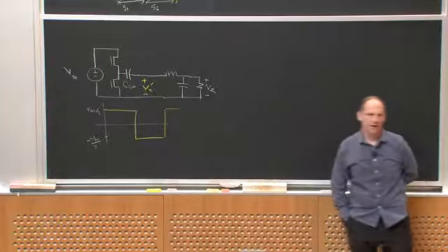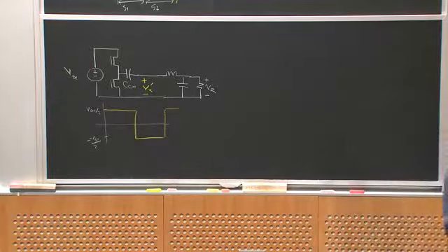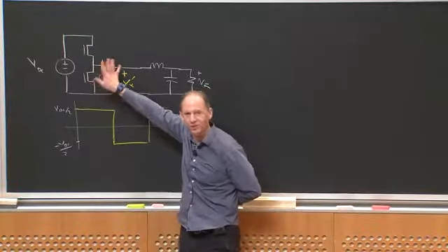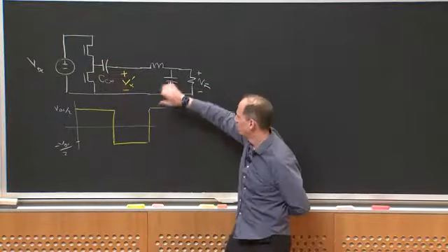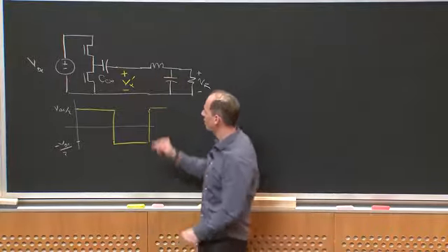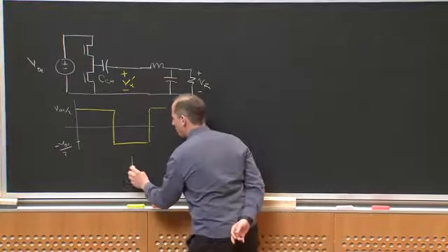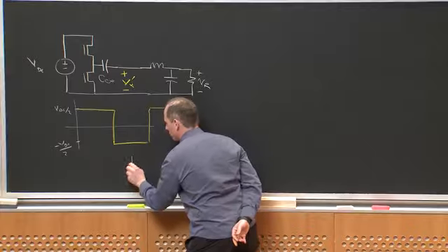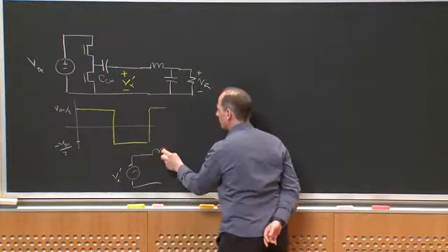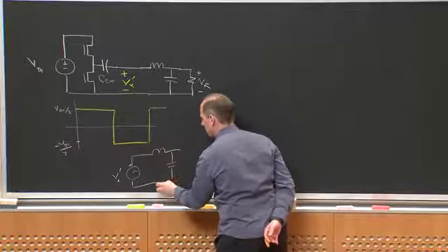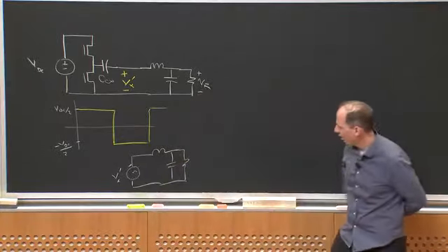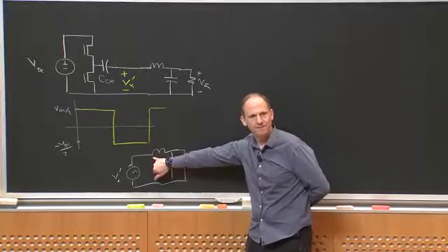This would be called a parallel resonant inverter. Instead of having a blocking capacitor here, I could have done this in different ways, including using a full bridge, etc. But I just want to illustrate this. Now, why is this a parallel resonant network? If I thought of Vx prime as a voltage source, if I make Vx prime 0, L, C, and R here are in parallel, right?